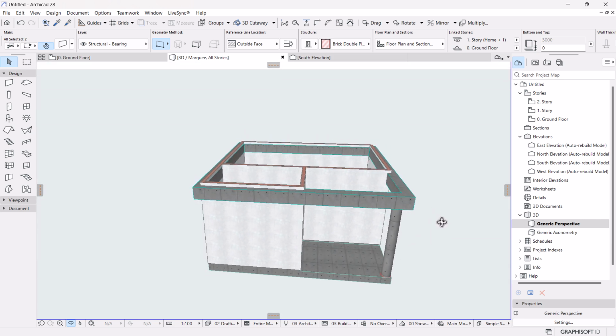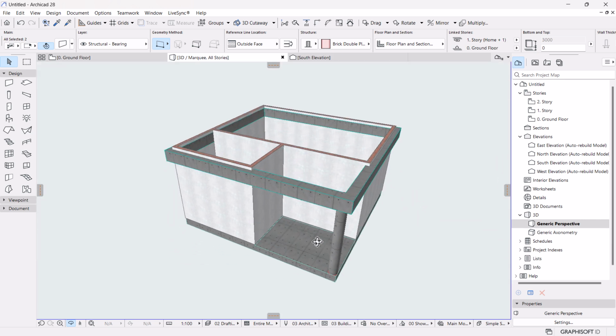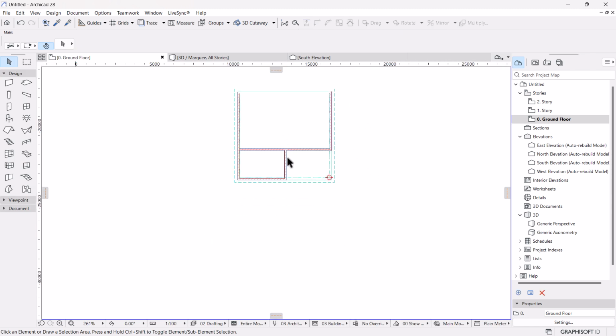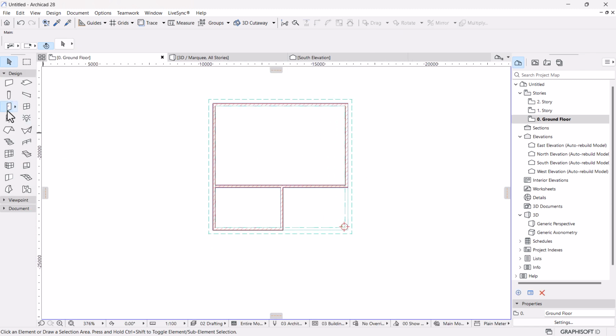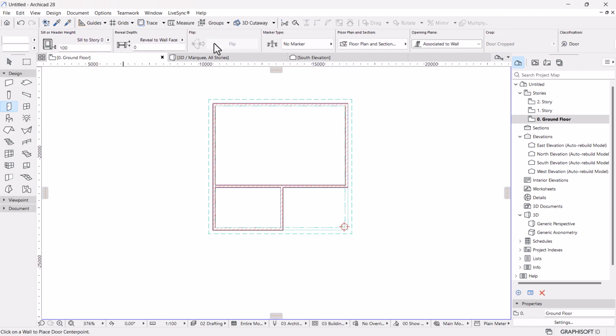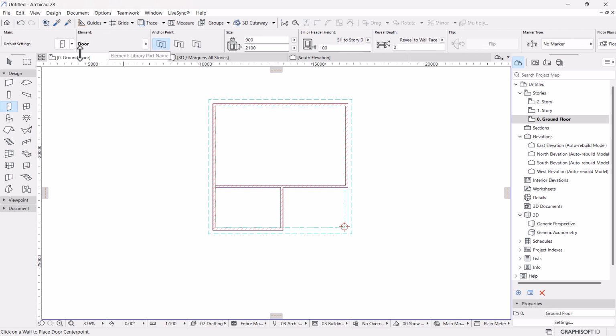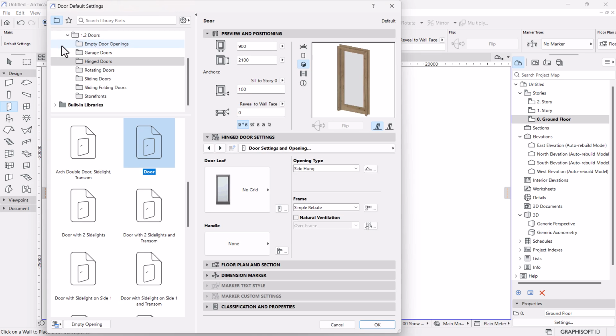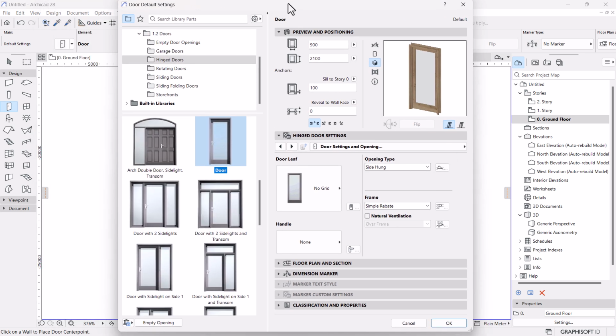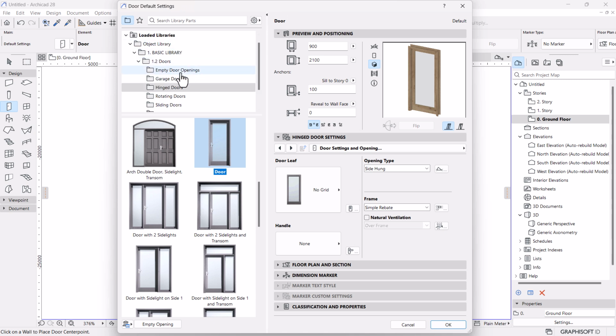All right. So now let's move on to the openings. Openings, very important. I will activate the doors. We'll have tons of parameters for doors here, but this one I would like us to exploit from an expanded view perspective. We have libraries that come with a template of different styles of doors.